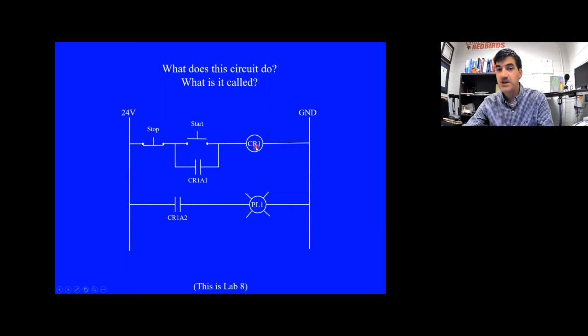And now all the normally open contacts return to an open state, and all normally closed contacts return to a closed state. So both of these will reopen. And now, even after I release the stop push button, I have broken the continuity, and so I will not have current flow through here, and I will not energize that until I press start again. And similarly, when this opened, I no longer have current flowing through here, and PL1 is de-energized.